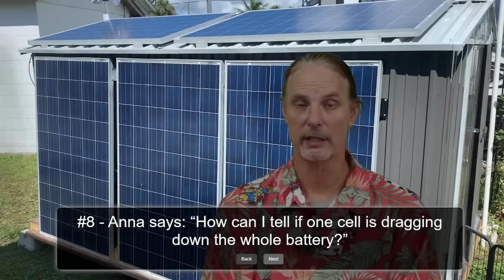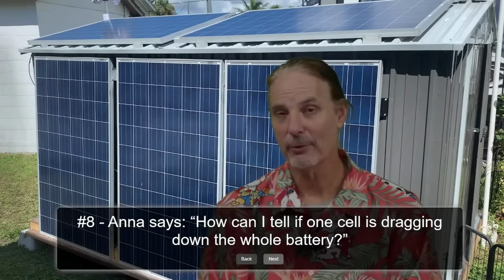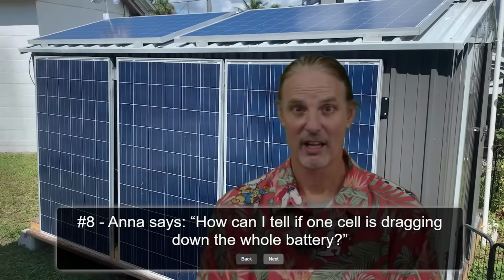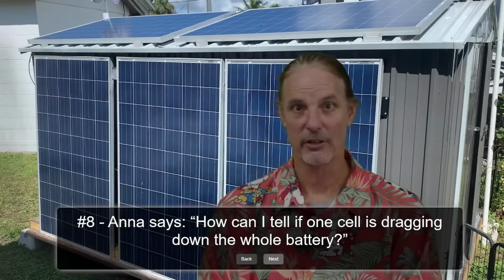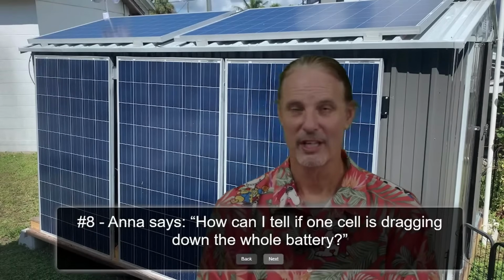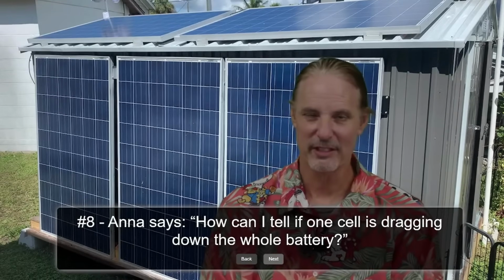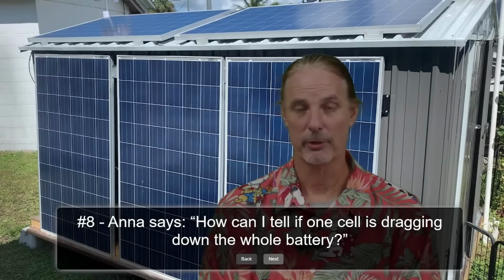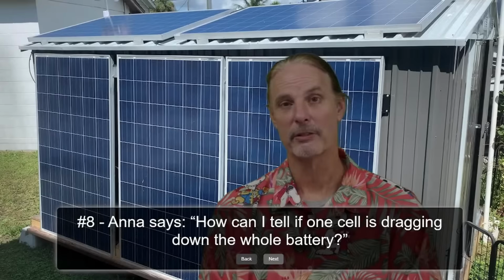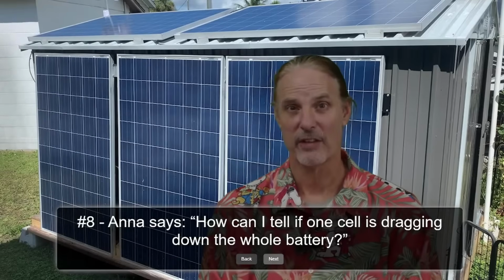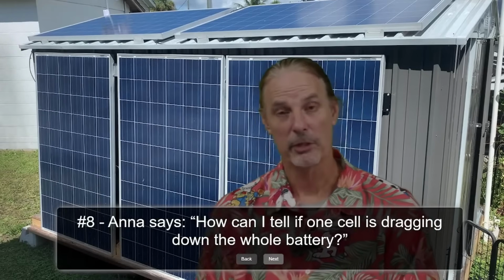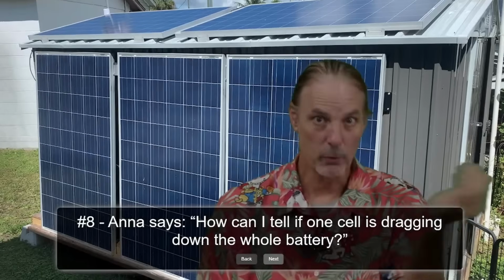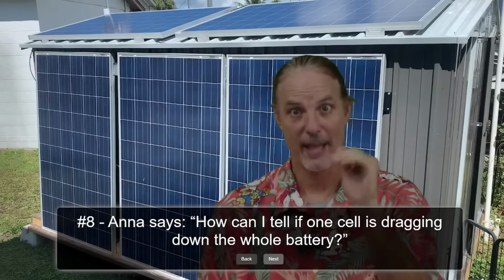Some batteries are maintainable, where you can go in and you can replace a bad cell. You can replace it with a cell that's of equal or larger size, larger being relative in nature. I don't mean go in and take a 100 amp hour cell and replace it with a 300 amp hour cell. I'm talking about take a 100 amp hour cell that has a year of degradation in it and replace it with a new one. It will be brought down to equal the other cells in that pack.